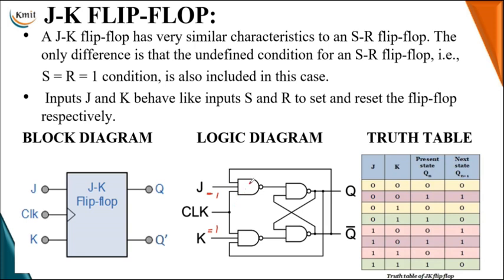Instead of two-input NAND gates on the first and second NAND gates, let me take three inputs, with NAND gates numbered 1, 2, 3, 4. The first NAND gate has 3 inputs, and the second NAND gate also has 3. The third input of the second NAND gate is fed back from the uncomplemented state of the present state, and the third input of the first NAND gate is connected from the complemented state of the present state.